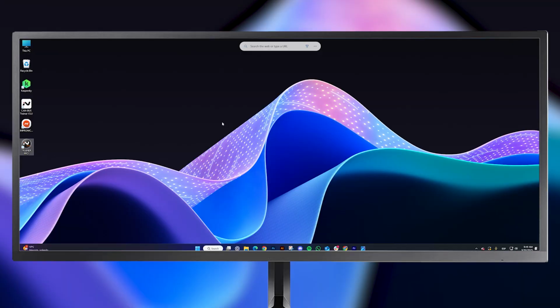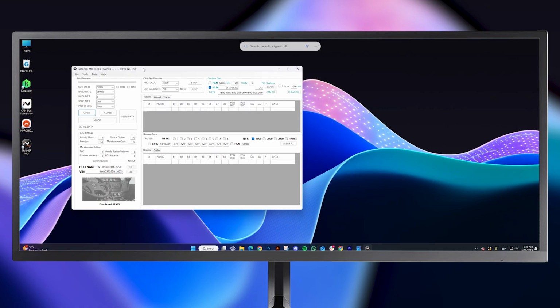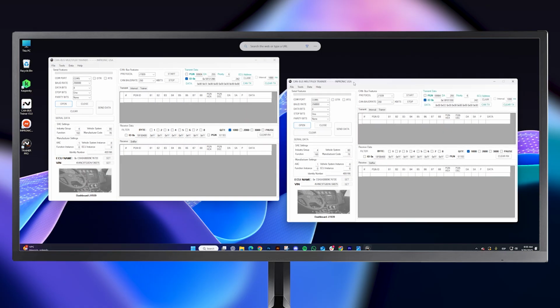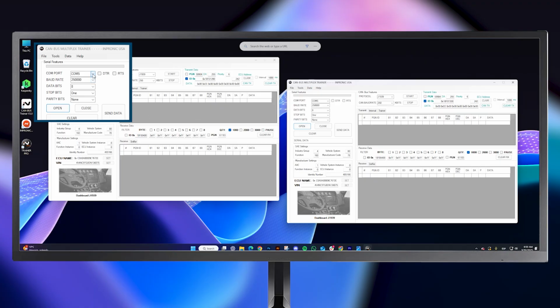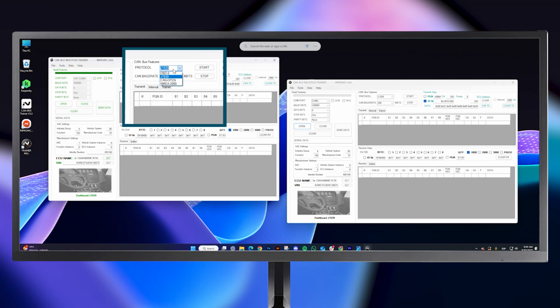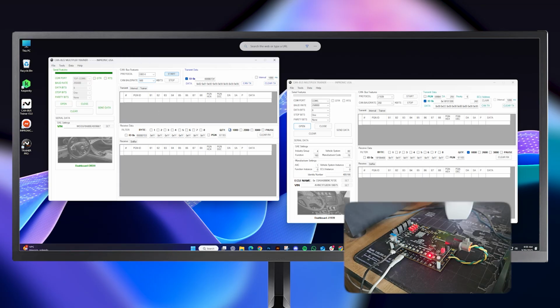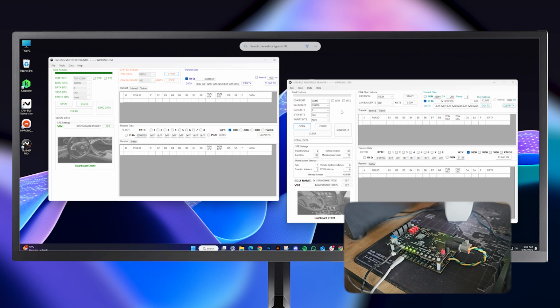We open our Pro Edition software in 2 windows to generate a real communication. Once the windows are open, we open our COM port, in my case, COM6. We press open and can see that it's the upper board. Let's start with the OBD2 protocol and a speed of 500 kilobits. Then we press start and the LED 7 will begin blinking rapidly.